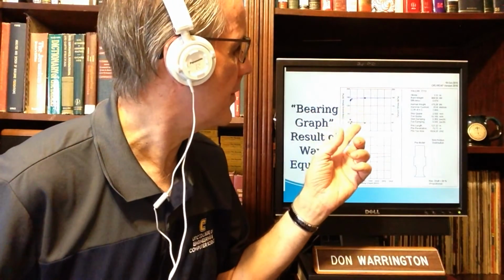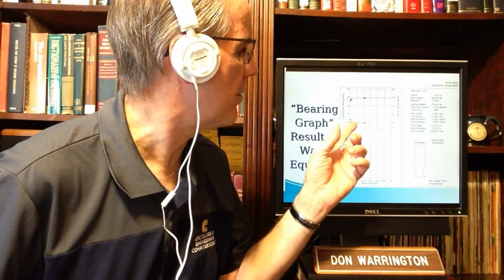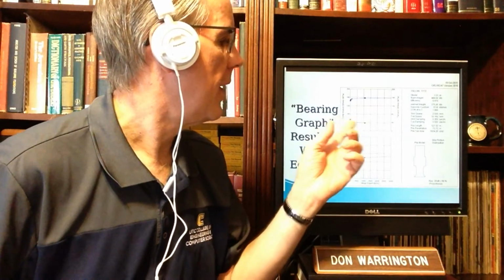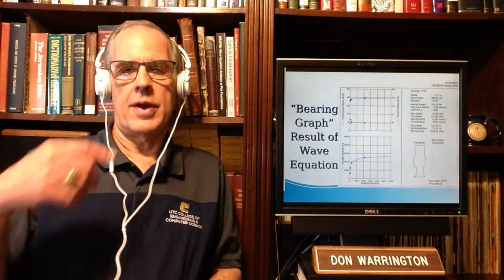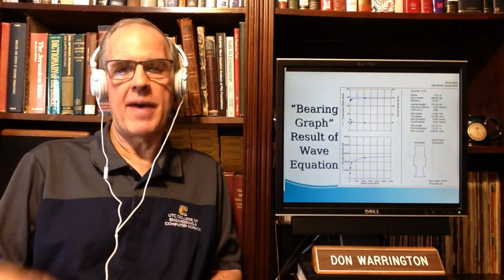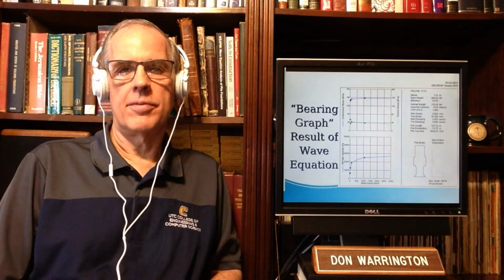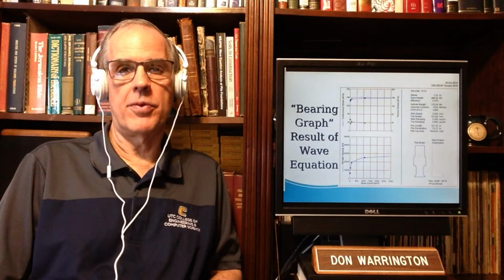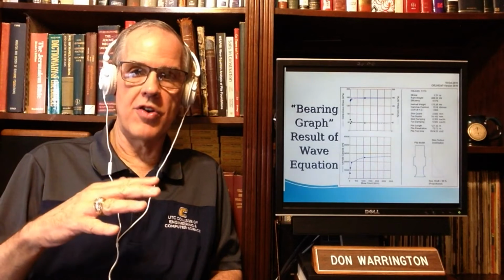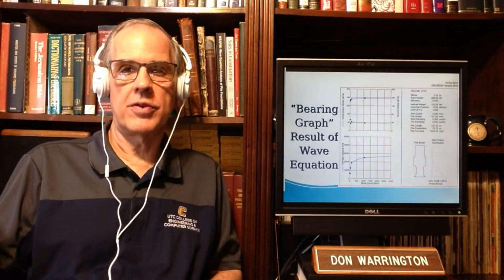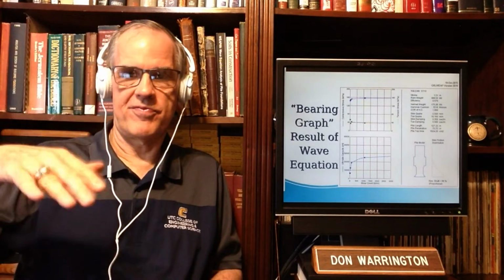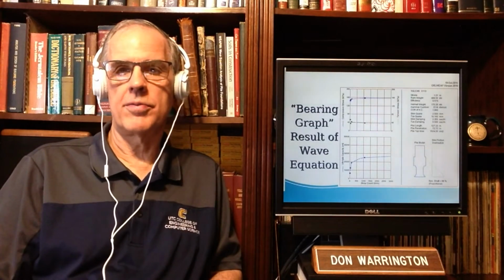The interesting one always is this one, which is the tension stresses. Now, the tension stresses are much lower than the compressive stresses. In early driving, as you saw with the pile wave demonstration, you get tension stresses coming back up from the pile toe. And with concrete piles, those are very important to monitor. In fact, what we normally do with a concrete pile is we start out with a lower energy and then increase the energy once we get past that initial very loose phase where you've got very low blow counts or high sets.